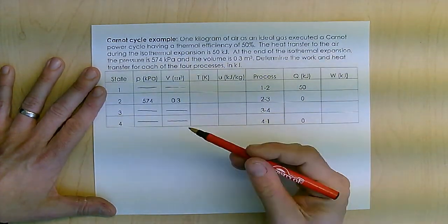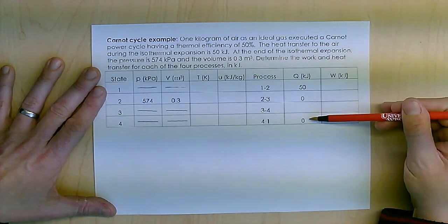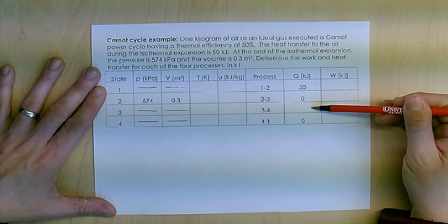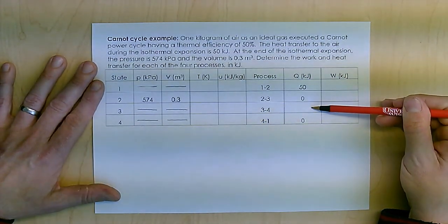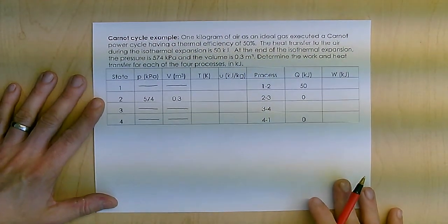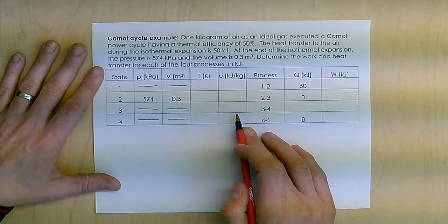So you'll remember I've got 0 plugged in because it flips back and forth between adiabatic, and then these two are isothermal. The first thing we do in anything like this is we set our states, which, because it's a closed system, means find my U values.